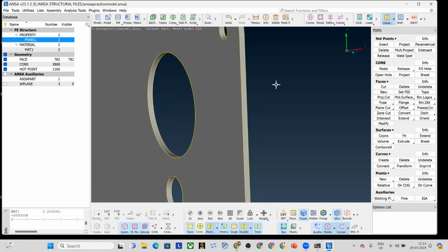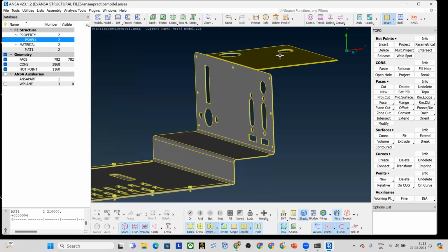I have a doubt whether this bright yellow color and this gray color surfaces are stitched properly or not. This component would have been modeled using SolidWorks, Creo, or CATIA, where you might find these two surfaces completely attached properly. But that works on different graphic standards, and this analysis software works on a different graphic standard. So once you bring that component over here, I might have to check whether these two surfaces have been properly stitched together or not. Similarly, you have all these stitches which you have to check.